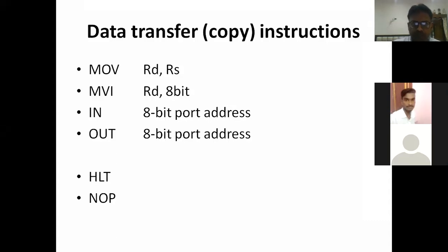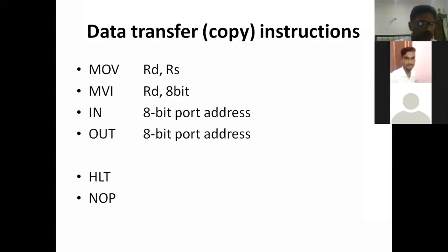One thing to be noted very specifically, which is very important: in case of the 8085 microprocessor, data transfer operation is not going to affect any flag. Second, it is going to change the content of the destination register, but it is not going to change the content of the source. The content of the source will remain as it is, but the content of the destination will be changed. Whatever the previous value was, it will be abolished and the new value will be placed at that place.